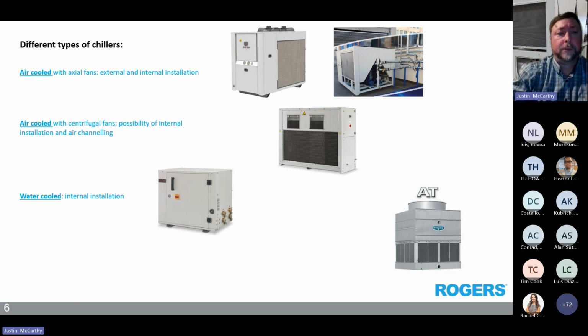Then there's water cooled internal chillers. We'll see a lot of these in larger plants. The general rule is water cooled chillers are more efficient than air cooled chillers, but often the higher capital costs can force people to buy an air cooled chiller as well.